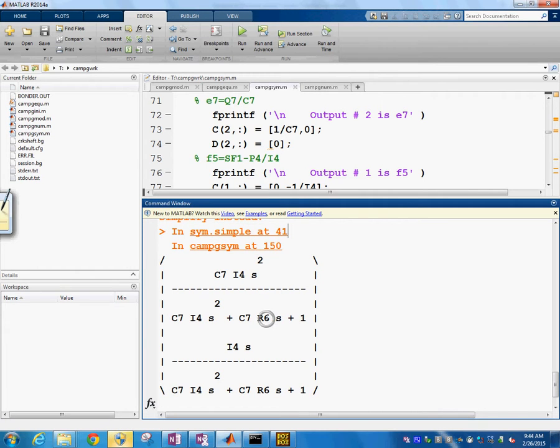And now we're not going to guess. We are going to deliberately direct the design ourselves, in the sense that, okay, do I want more damping on the system, or do I need more stiffness on the system? What do I want to do? And depending on what I do, the behavior of the system is going to change. And that's what I would like to do.